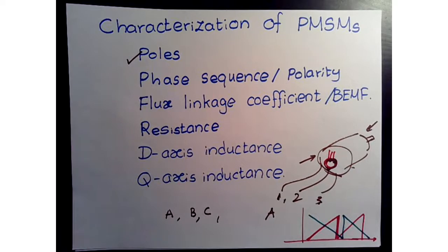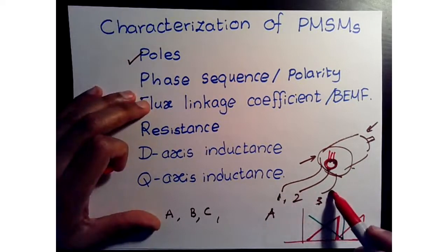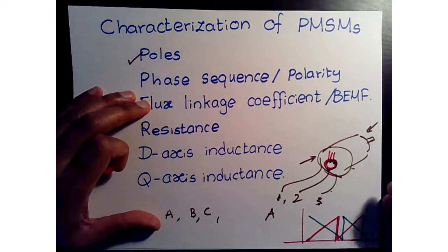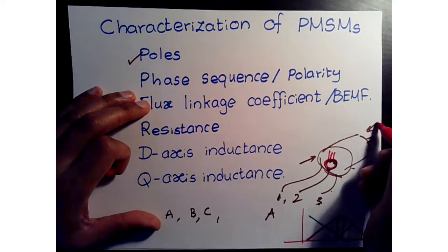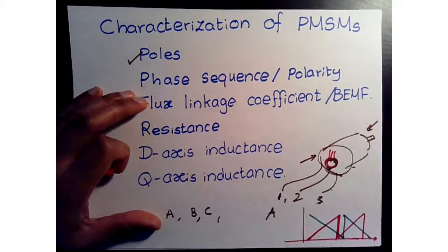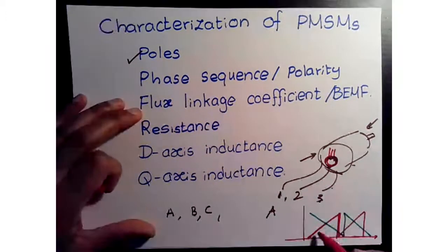Now, what I would follow: I would say I apply a certain phase sequence and I see positive slope of the sensor. I'd be inclined to call that positive polarity, and then you can look from the front of the motor and see, okay, is it going clockwise or counterclockwise? That is my ABC sequence. The reason is when you have a positive slope, that gives you positive speed.